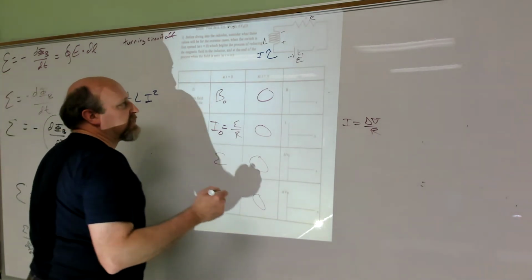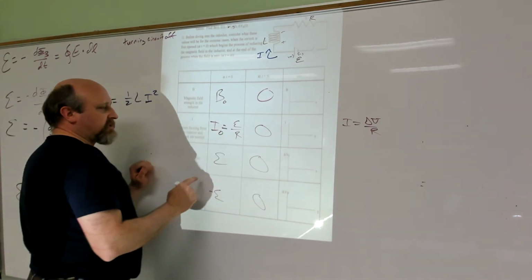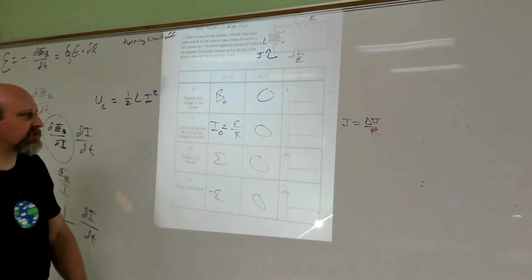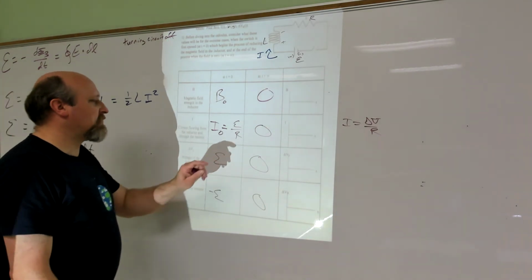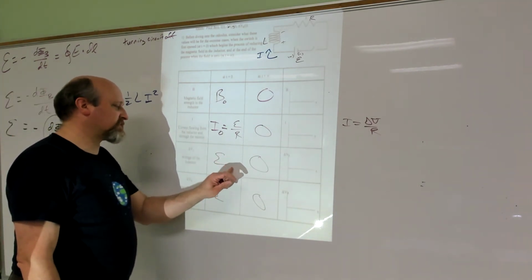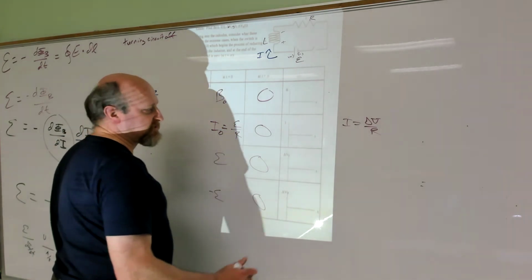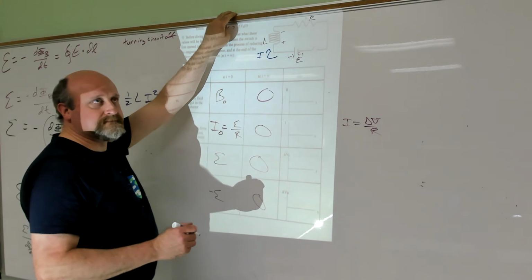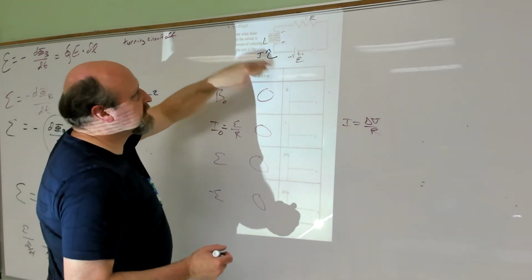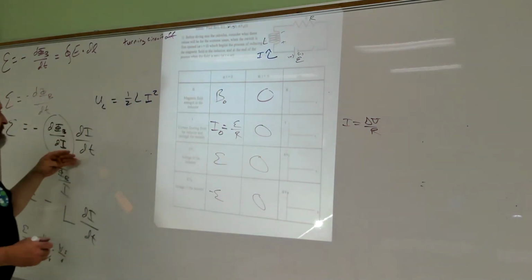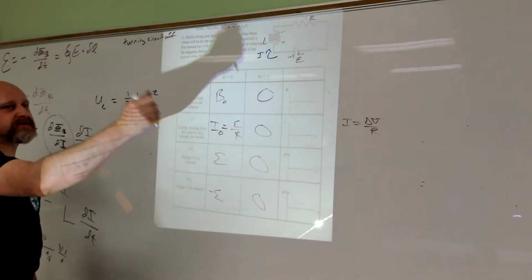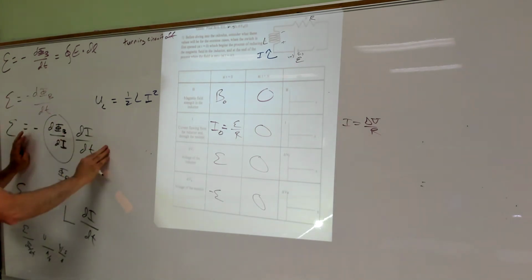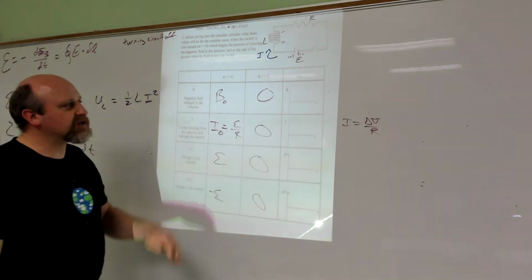Okay, hey, what do these graphs look like? Starting with this one, the voltage across the inductor. At first, there was no delta V across the inductor, right? This was moving, nice steady current flowing through, di dt was 0, and then somebody opens the switch, and it's going to make a back EMF big enough to keep the current flowing like it was, so it just slowly has to decrease from there.